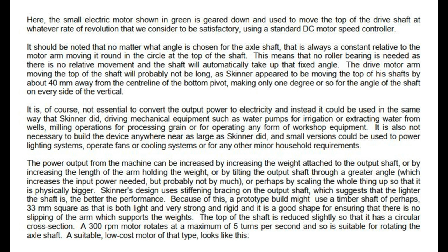It should be noted that no matter what angle is chosen for the axle shaft, that is always a constant relative to the motor arm moving it round in the circle at the top of the shaft. This means that no roller bearing is needed, as there is no relative movement and the shaft will automatically take up that fixed angle. The drive motor arm moving the top of the shaft will probably not be long, as Skinner appeared to be moving the top of his shafts by about 40 mm away from the centerline of the bottom pivot, making only 1 degree or so for the angle of the shaft on every side of the vertical.